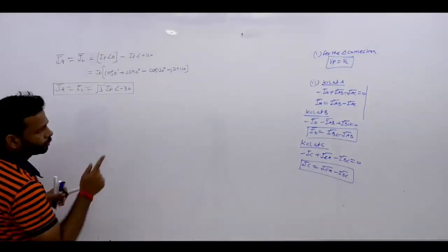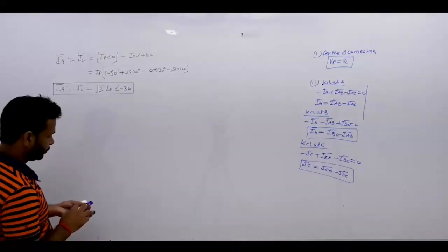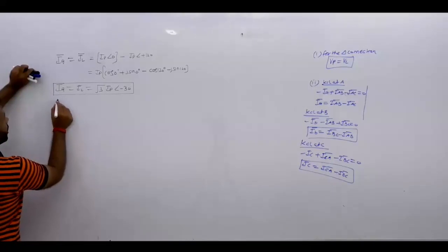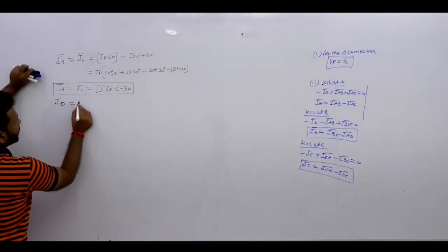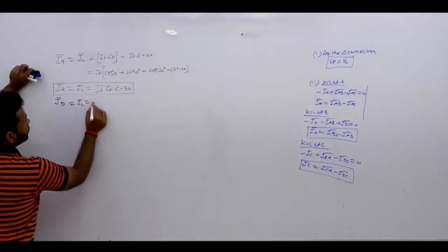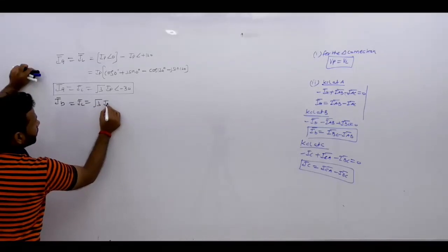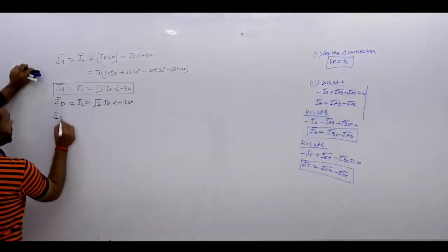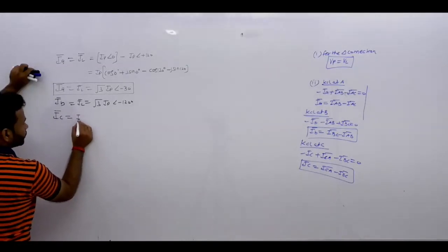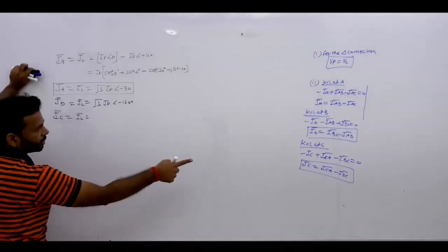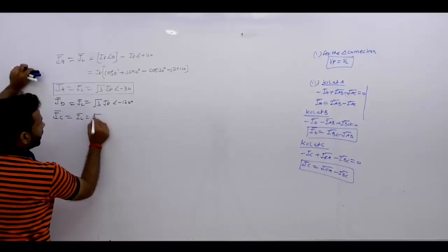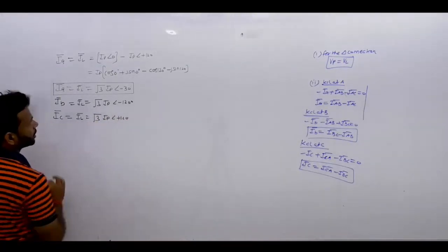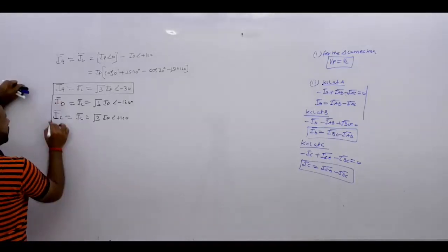Now similarly, if you take the second expression, same as first, then your IB is IL is equals to root 3 IP angle minus 120 degree. Similarly, you take IC is equals to IL, the third expression, then you will get root 3 IP angle plus 120 degree. ठीक है यहाँ तक. So these are the results for the delta connection.